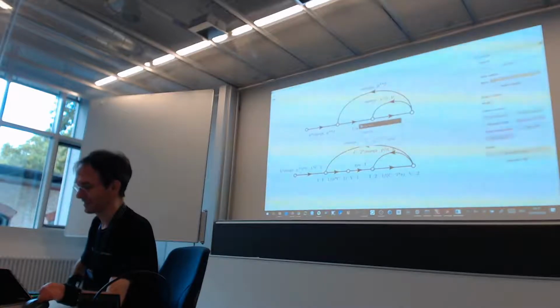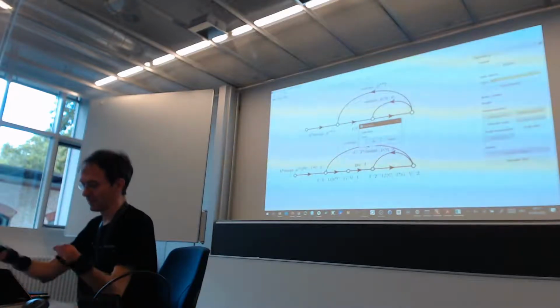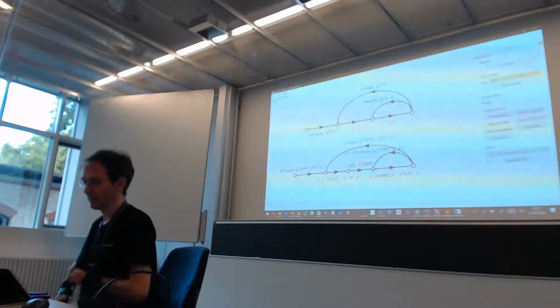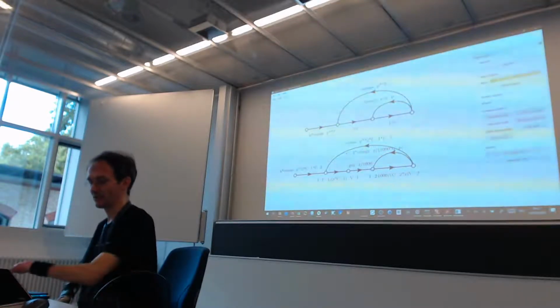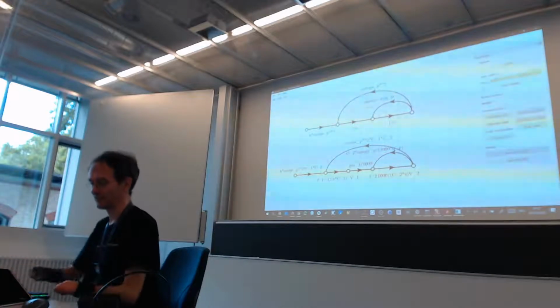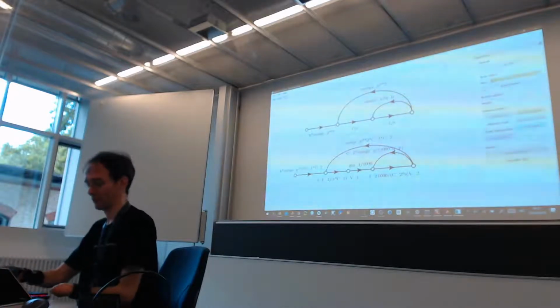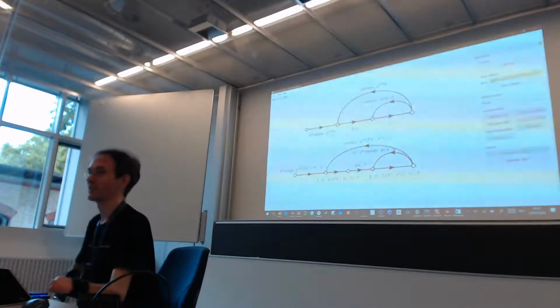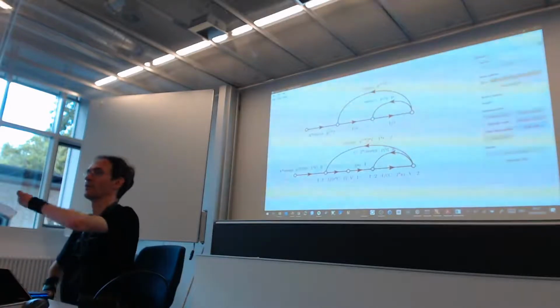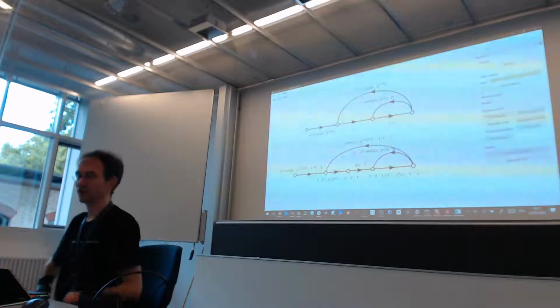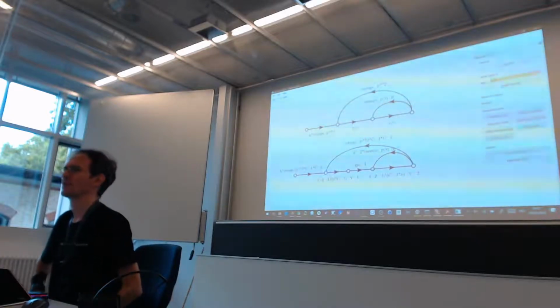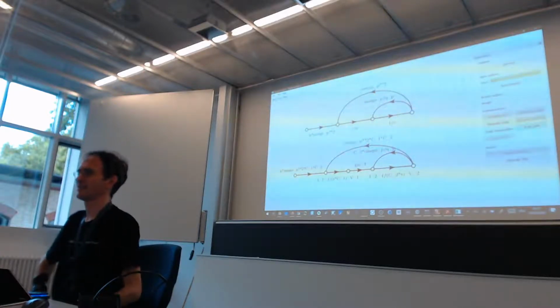So I scale it, and I want it just to be divided by 1,000, without changing anything else. So now you see how you should change all the others if this value I2 would be too large for you. I revert that. And by going through the signal flow graph, you could now figure out which node, which level, which voltage, which current you would basically like to have at the correct level.